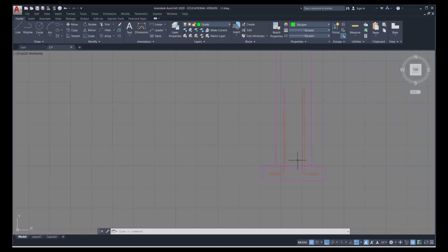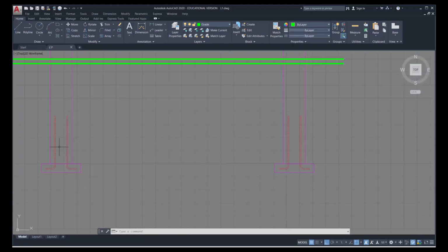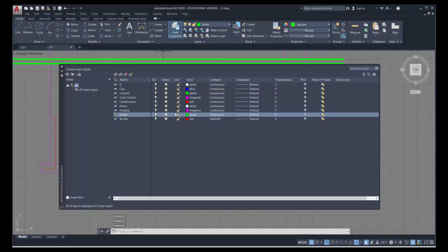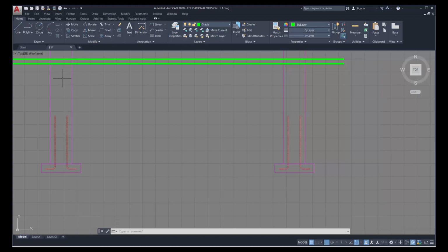If I zoom in onto the rebar, you'll see it's a hidden line. The scale of the hidden line is incorrect. We're going to correct that. Now, since we've loaded that line type, I can also take existing lines. So I'm just clicking on them and modify their line type. Notice it's in the concrete foundation layer. I don't want to change this menu here because in concrete foundation, I also have lines above grade which are not hidden. But I still want everything in the same layer.